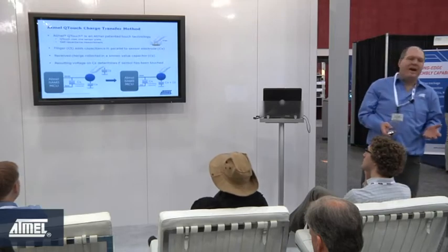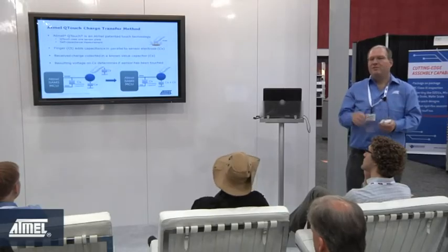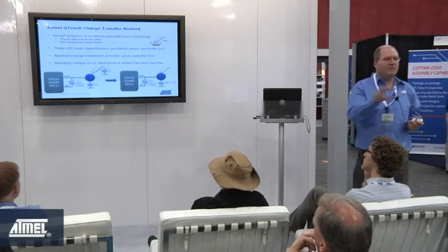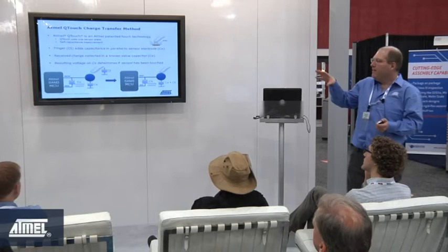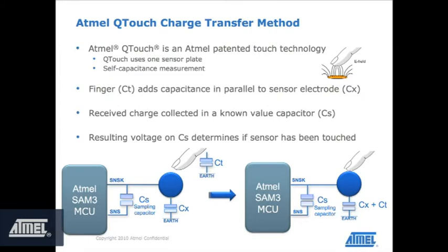Essentially, there's a touchpad sitting there, not touched by anybody, with a sampling cap in the circuit, and the system is feeding a signal out. It's a complex spread spectrum signal, and it's getting its readings. As we touch it, we're changing, through our own personal electric field, the capacitance on that button, and that is definitively determined as a touch event because the capacitance changed and the induced voltage has changed.